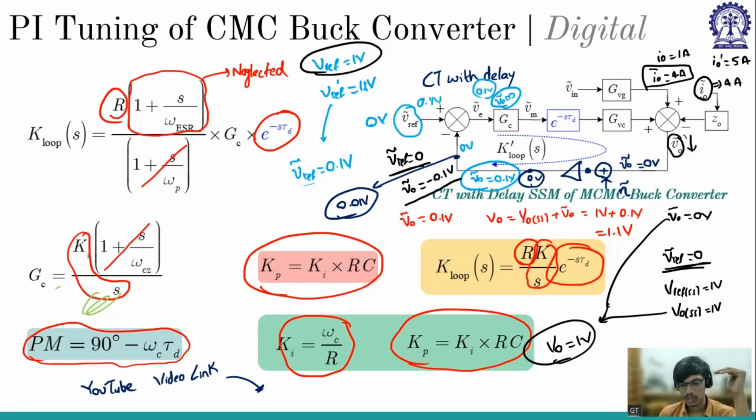So there will be a maximum limit, or the maximum speed, with which the controller can go from one steady state to another steady state using the small signal model, and that is the limit beyond which you cannot do anything. If I want it to be much faster, the model is not valid, so you cannot use that model, and you have to go with the large signal tuning, where there is no model limitation.